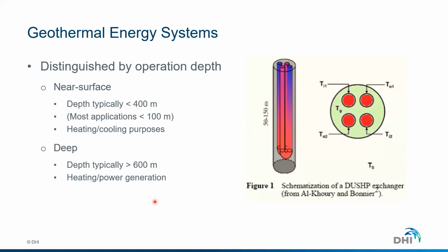FEFLOW will allow you to model a number of different systems on near surface, or better said low enthalpy systems, with typical depths less than 400 meters. You can have a number of boreholes working at that depth, but we also have possibilities to go even deeper. There are some models out there and also a number of publications using FEFLOW at several kilometers.